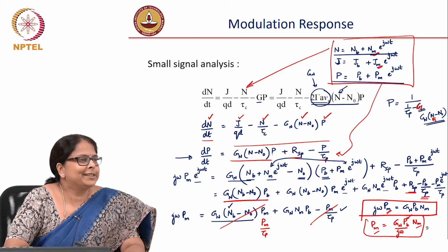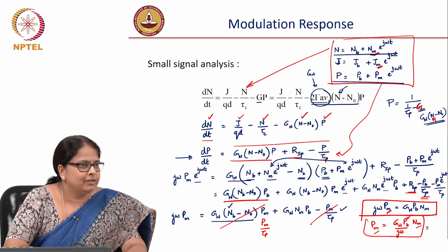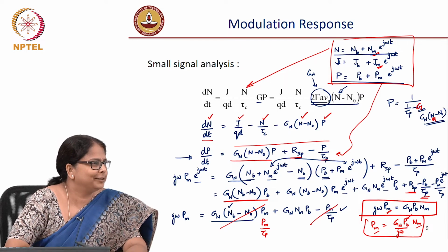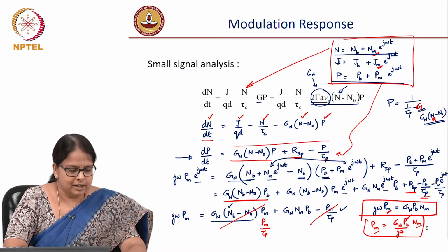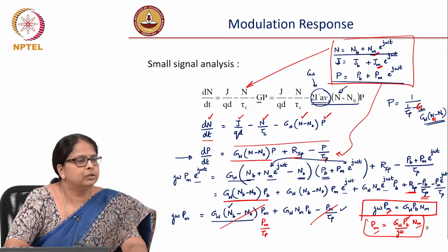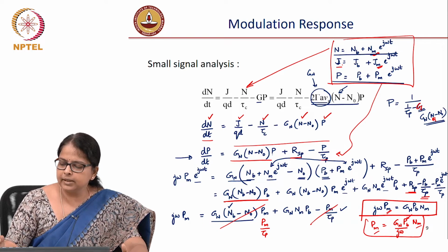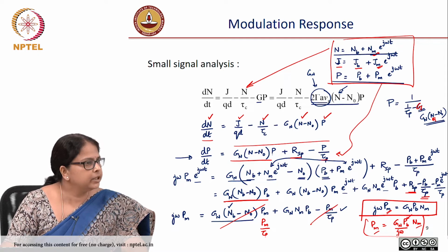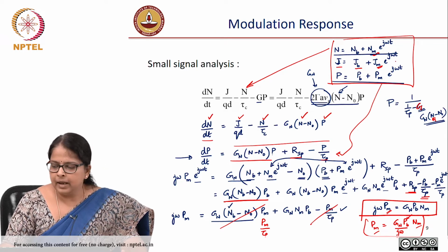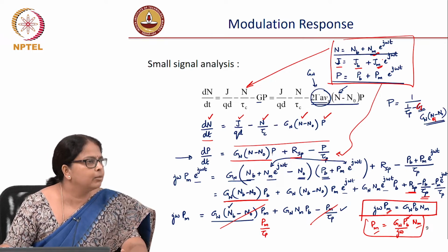Okay. So, last time we started deriving the modulation response of a laser diode with the idea that we wanted it to be larger than that of the LED. It was a little bit of an algebraic exercise. So, the crux of it is that we do a small signal harmonic analysis. Given a current as the input which is about a certain bias, there is a small modulation Jm. You assume that Jm is very small when compared to Jb, there is a small signal part, and you are assuming that the injection current is sinusoidal. So, you are doing a harmonic analysis.